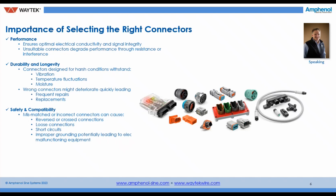Safety and compatibility: mismatched or incorrect connectors can cause reversed or cross connections. Now, how can we mitigate that? By color coding housings or even wedge locks, having different wedge locks that are going to provide keying to make sure that the integrity of that connection is what we should have.